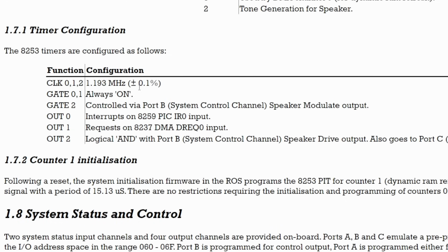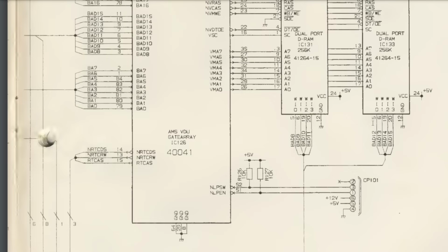Now, this is not necessarily a huge problem because we don't actually need the interval timer to do cycle accurate timing. It's really just a negotiation between the CPU and the graphics subsystem. By the way, that 1843.2 kilohertz crystal that we found, according to the technical reference manual, is for serial I/O, and that's irrelevant to us. We can just totally ignore that. The two crystals that matter are the 24 megahertz one, which is divided by 3 for the CPU, and the one that I've been calling the 2 times NTSC crystal, the 28.6 megahertz one. And we know now that that runs the programmable interval timer.